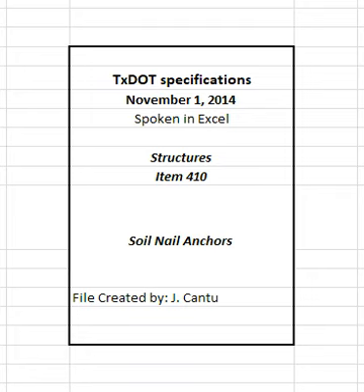Failure to provide an adequate reaction pad will void the soil nail anchor test. Provide additional test soil nail anchors until an adequate reaction system is achieved. Furnish additional test soil nail anchors, required due to inadequate reaction pads, at no expense to the department. Provide a reaction pad with a center opening larger than the hole diameter to ensure that no bridging or interaction occurs between the grout column and the reaction pad.